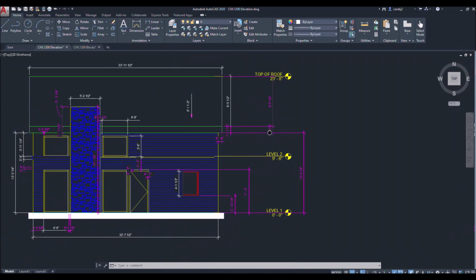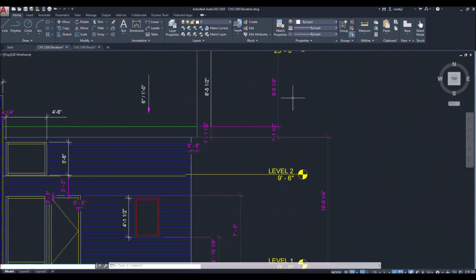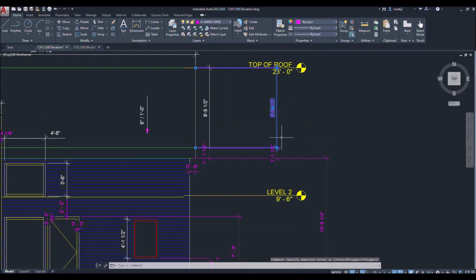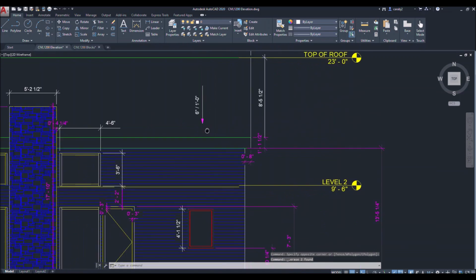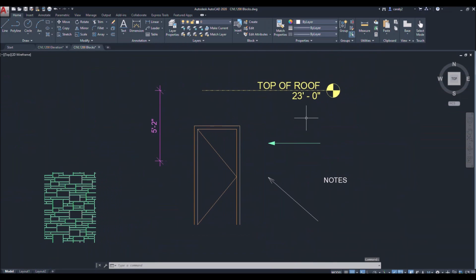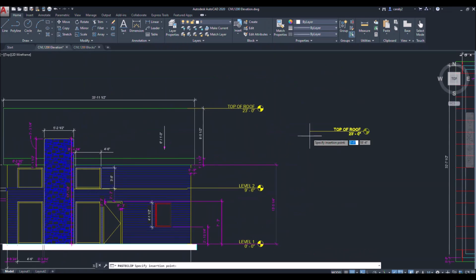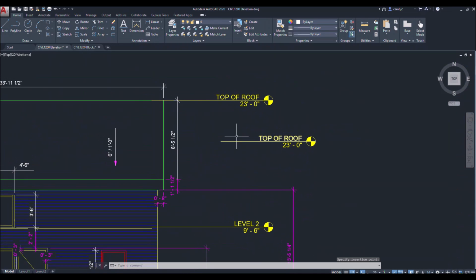But then for this drawing, since it's just these two drawings for the set, you can just copy the ones that I give you on the blocks file and match the properties, edit the points in order to create your dimension strings. And that goes the same for any of these as well. You can match the properties for anything basically in your file. So here, if I press paste, if I actually type in MA here and go over here, it's going to want to change it to match the properties of this one as well.